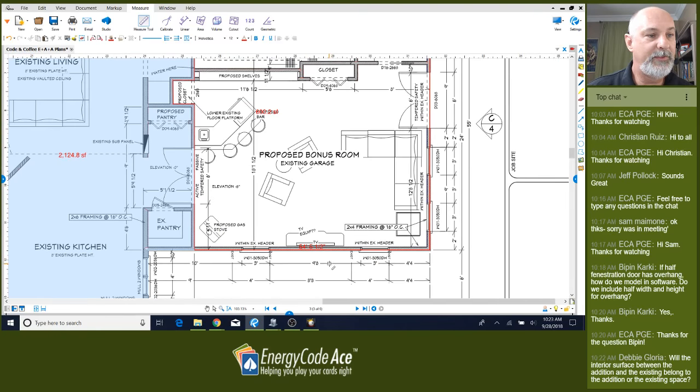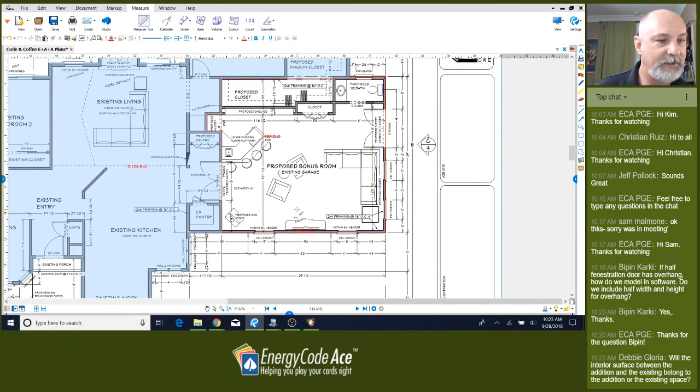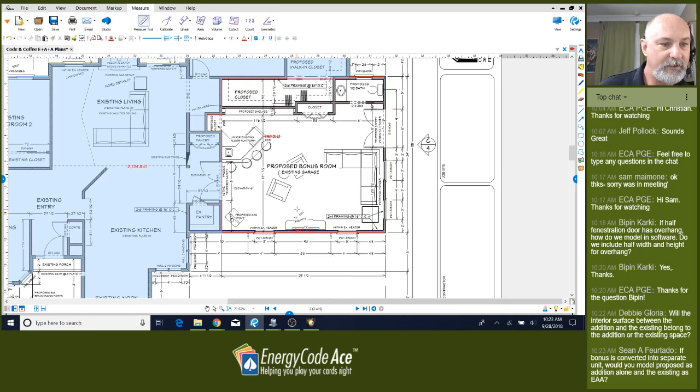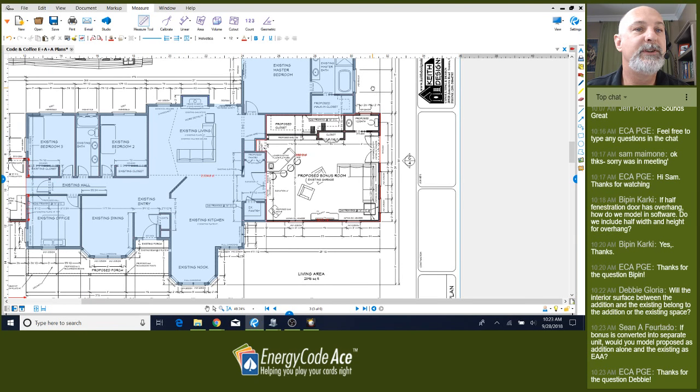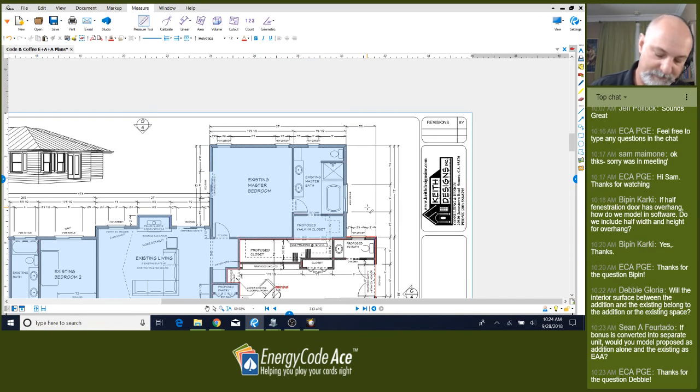Let's start with our front wall. That's what, 25 feet. I'm rounding a little bit here. It's 25 feet 1/2 inch. So if you have a foot and inch calculator, you can convert that. Great. I'm just going with round numbers. 200 square feet for the front wall. We don't have any left wall. We have a back wall, and that dimension, see if I can find it here, 5.5 feet.